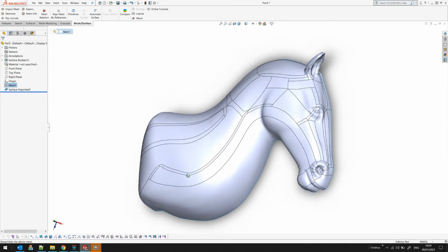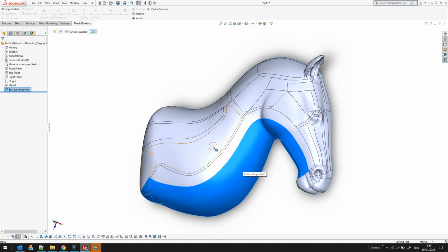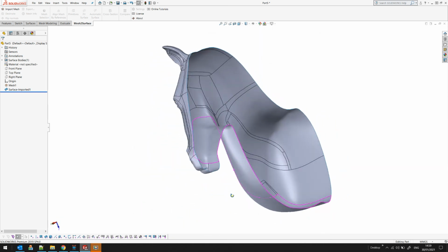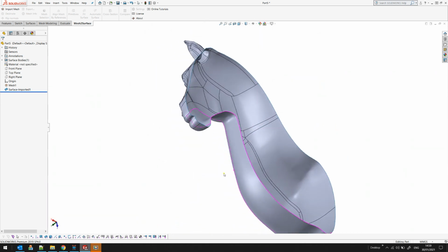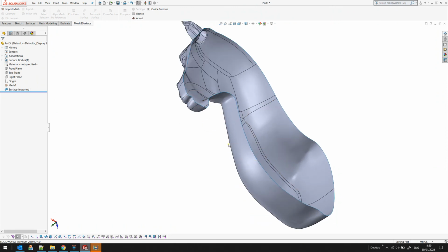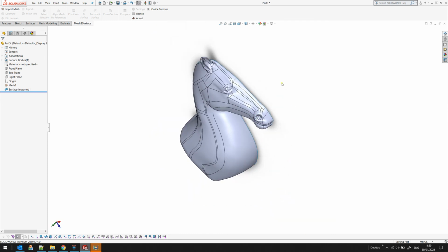That was all about the automatic surfacing. You need to play with different objects to get different results, but we transfer them into big surfaces here that will become faces. This means that we reduce the number of surfaces that are in SolidWorks, and this helps SolidWorks to handle the object in a much easier way. You can apply Boolean operations, you can cut this from a mold, for example, and you can use it in your project. I hope this is useful.